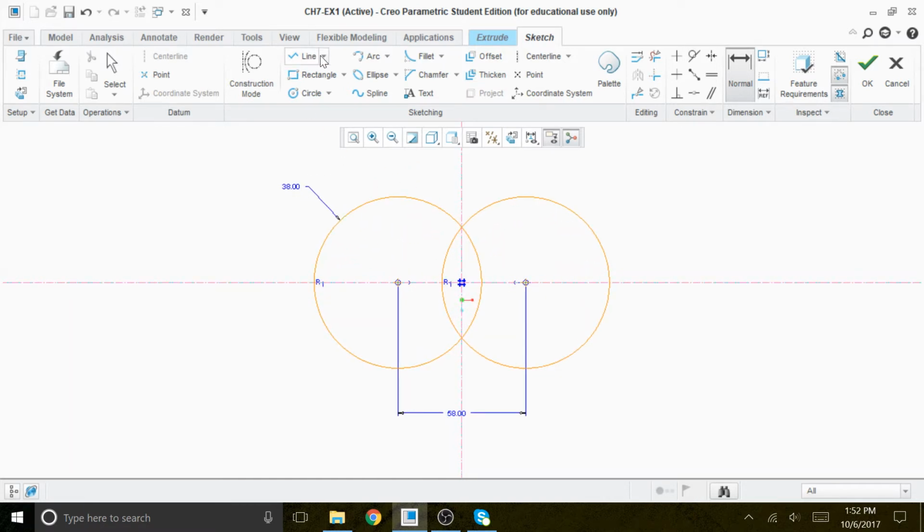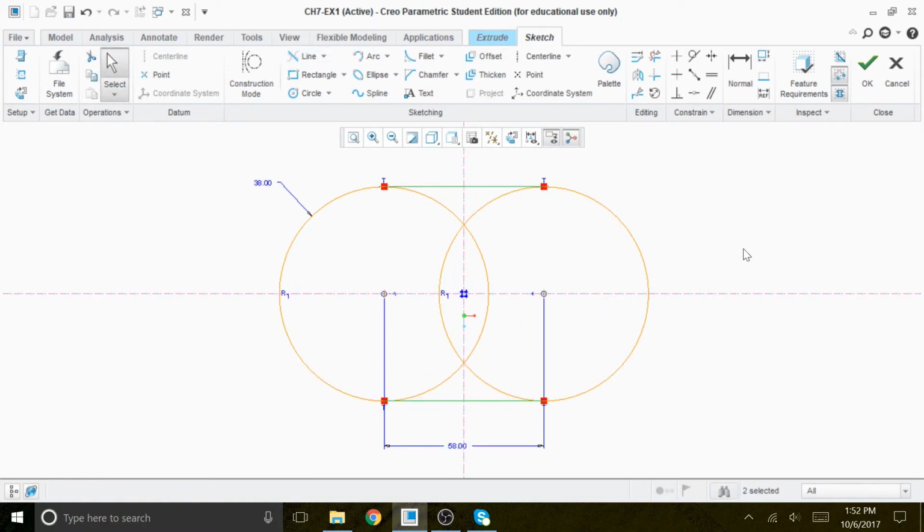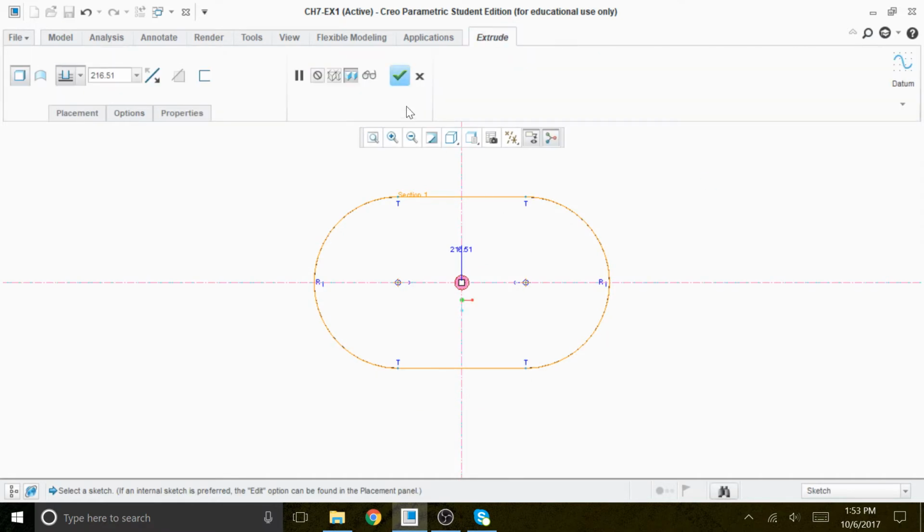And now we're going to create a line tangent to this curve. Okay, and now we're going to delete or trim this piece inside this circle so we can clear it. Okay, all right, so we are ready to go. And now we have the radius for both curves the same, and R1 means same radii, and the point of tangency should be there.